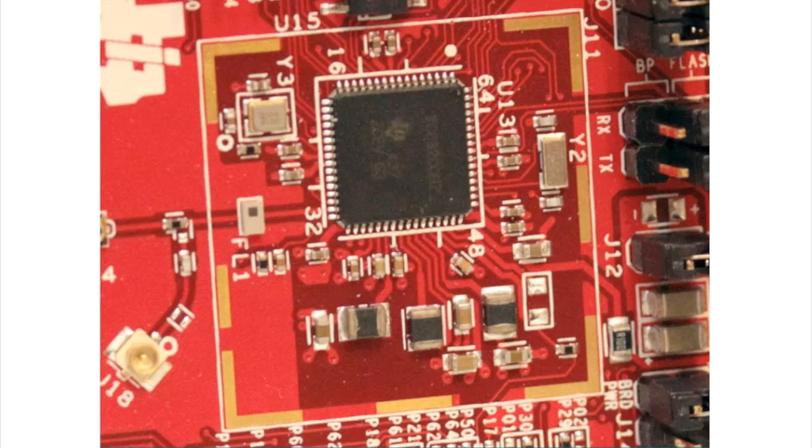So if you haven't heard all the buzz about this guy, it's the CC3200. It's supposed to be able to last for more than a year on 2 AA batteries. That's quite an amazing claim, but do take a look at the data sheet. You'll find that this kind of longevity is based on about a 20% duty cycle, and that's about a sample every 10 minutes or so. And if that sounds like the IoT device that you're working on, then you should be fine.